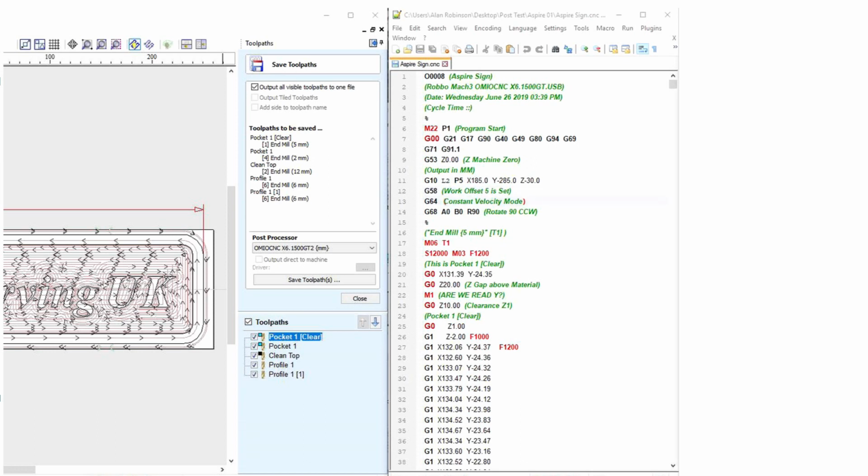Line 13, this is set from within the post processor depending which mode you selected. G61 and G64 path control mode, program G61 to put the machining system into exact stop mode, or G64 for constant velocity mode. It is OK to program for the mode that is already active. Line 14, this is set from within the post processor depending which option you selected. G68 and G69 rotate coordinate system, this has already been explained.